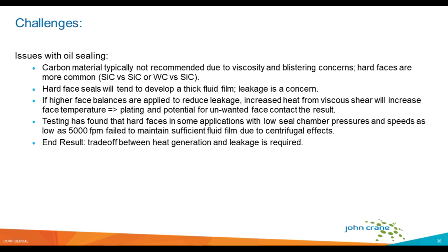So typically, from a material perspective, most seal designers and suppliers would like to utilize carbon for at least one of the seal faces, because carbon tends to wear in and have good lubricating properties, and also tends to provide the lowest leakage.